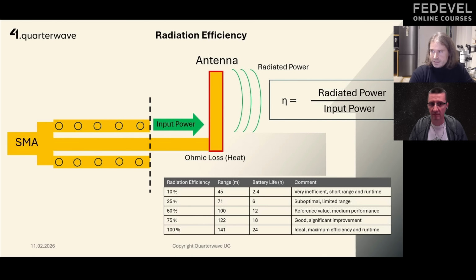There are different antenna designs for different use cases. So you can't use one antenna design for everything. You need to understand also the environment of the antenna, because the antenna lives from the environment. And always the first question that we ask our customers: do we have a STEP file of your environment, of your product? Because otherwise you get in trouble, because it's not like an SMD component. It's not like a resistor that you can place everywhere. You need to understand the electromagnetic behavior.